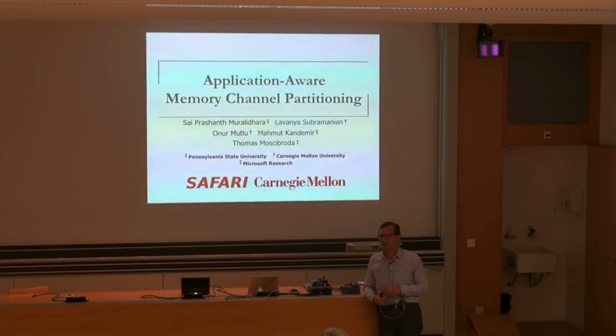I see. Basically, things are restricted to one bank or one channel in this case, and you're not utilizing the other channel. For example, you have problems because you don't see the memory as one contiguous region anymore, and the memory allocator is optimized for that case.